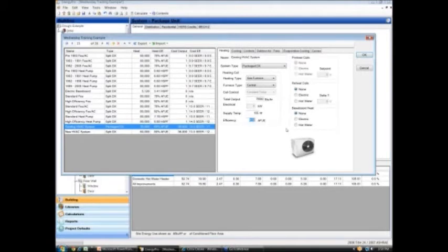This number down here, my AFUE, does it change my calculations? It's the whole ball of wax on the calculations. So that's critically important, to know what my AFUE is. And again, it is hard to know that on old units. Luckily, all I have to do is tell you what to put in here, not how to get it in there.